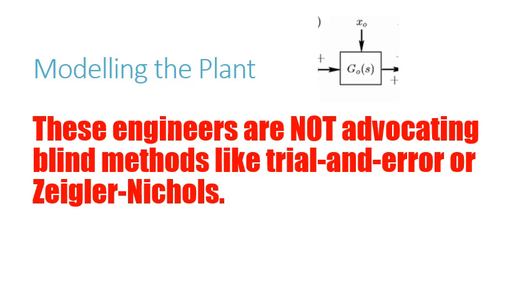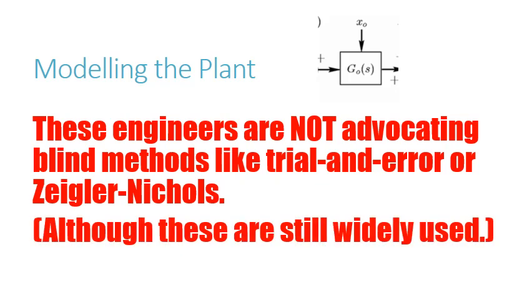For example, if you're controlling the temperature in a tank, and it needs to be controlled within plus or minus 2 degrees, but you have to force it into oscillation, and it's oscillating by 20 degrees up and down. That's obviously going to be really damaging to your process. You definitely don't want to do that, but it's part of these old methods that are still frequently used.